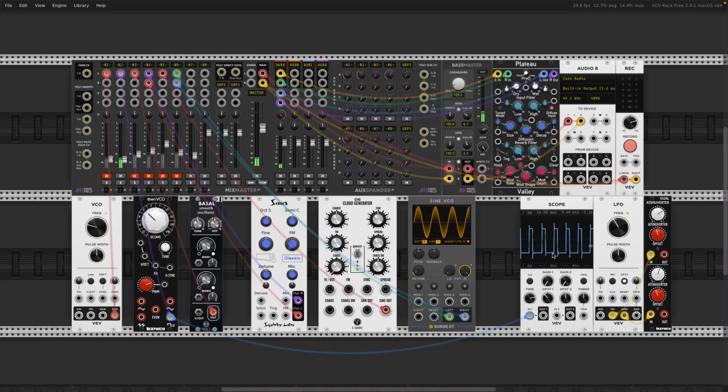The up and down movement still takes the same amount of time. Just now when we move up, we keep it up there for a shorter amount of time, and then we move it down and keep it longer. Up, short, down, longer. But of course much faster than that, at the frequency that we are setting here, so 100 times or more per second. So that's the pulse width, and you can control it here with this knob.